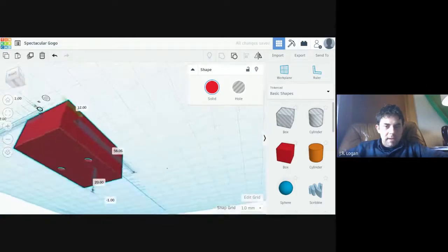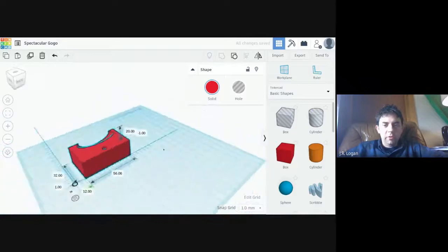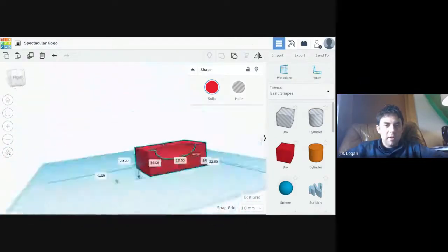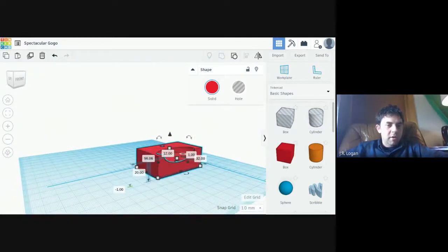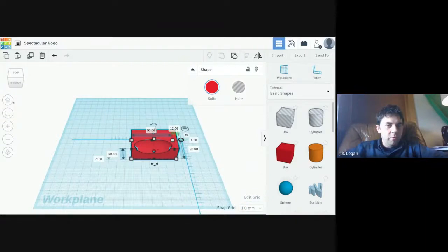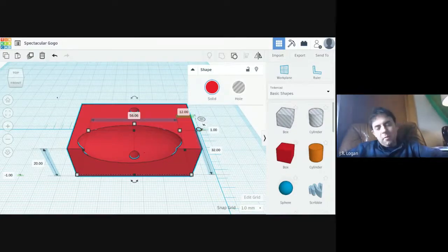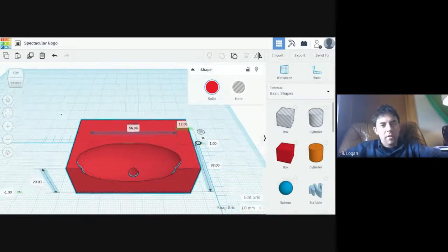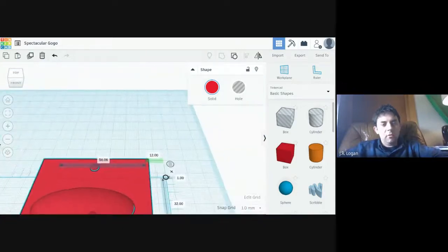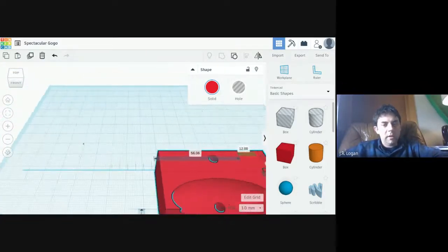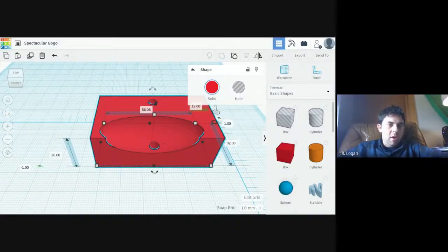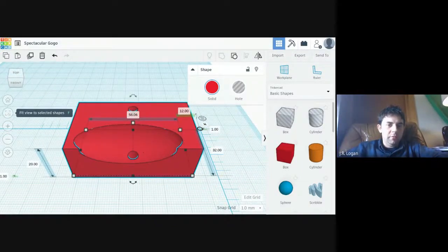Okay. All right, so one other thing that's useful, you can see that my camera is not aligned right now to where my box is. So I can always select the box, and then I can go to the home view, or I can go to the selection view. I can also, in my case, depress the wheel on the mouse, and that allows me to move side to side manually. But often you'll find that just clicking on this little button to go down to the object that you're viewing will be useful in getting to the object that you want.